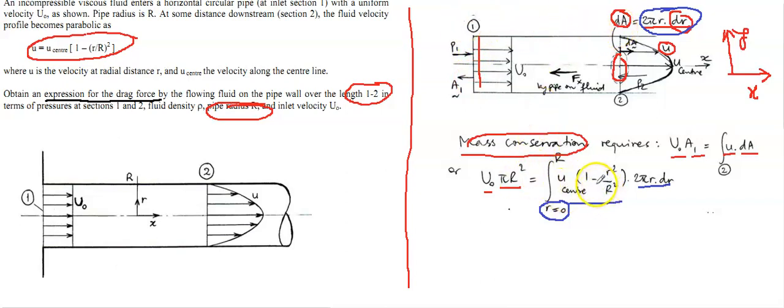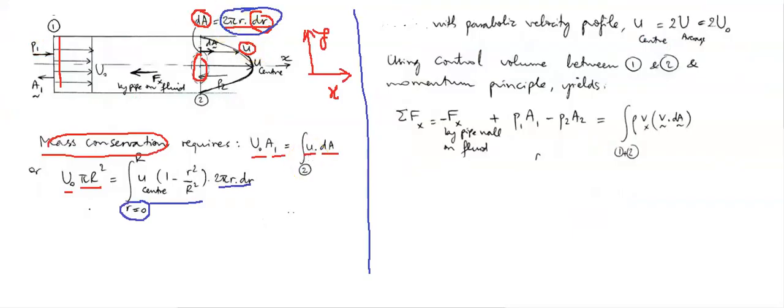Once we know this, we need to calculate an expression. So an important theory is when the velocity will be fully developed. This is the fully developed velocity profile, and I said initially that the velocity here will be maximum. According to the theory, when the velocity is parabolic or fully developed, the velocity at the center will be twice the initial velocity.